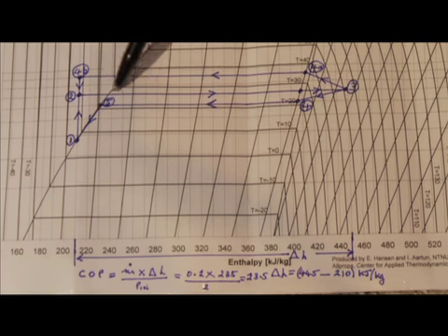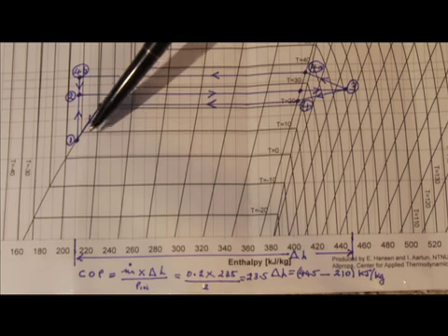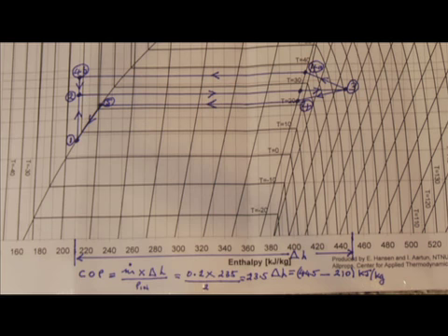We evaporate along this line here from 0.2 to 0.3, and then we condense. At the beginning of the 5-day cycle, we were condensing between 0.3 and 0.4, back to 0.5, and then back to 0.1. However, as the system acquired heat, the whole of this graph was moved up, and instead of condensing between points 3 and 4, we were condensing between points 3, 4a, 4b, returning to 2.